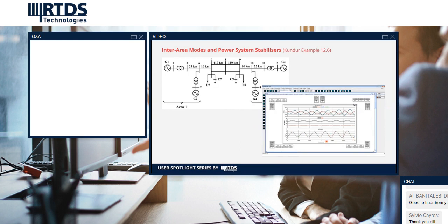And you can monitor the angle across the system, the speeds of the generator and the power transfer across the line, and you can see these unstable oscillations slowly growing. And the system has just enough negative stability that it can run for several minutes before it actually collapses. It gives you time to demonstrate the issue, and then you can turn one stabilizer back on again, and the system will come back if you intervene in time.